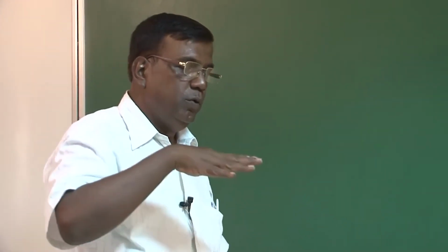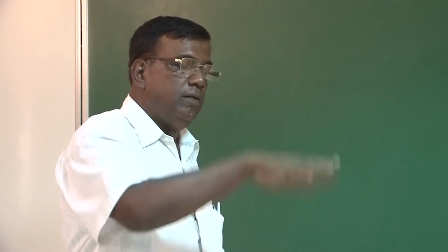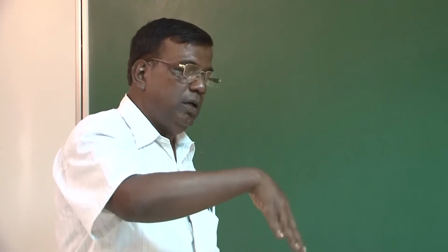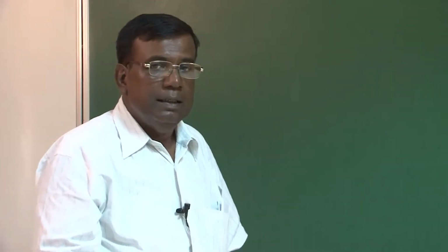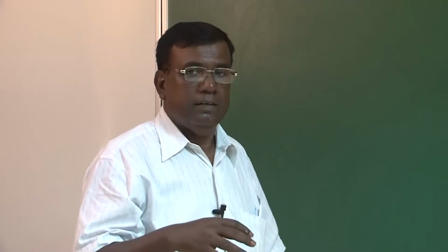When I say longitudinal motion, we all understand we are talking about a motion restrained to the vertical plane, and there are three motions which we are considering. One is motion along x, translation motion; motion along z, which is plunging motion; and motion about the y-axis, which is pitching motion. These three motions we are considering to restrict our discussion to the longitudinal case, with an assumption that the disturbances are small, so that there are no influences of longitudinal disturbance on the lateral or directional case, right?